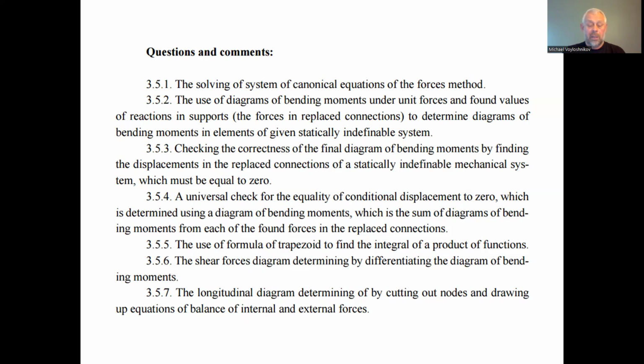3.5.7, the longitudinal force diagram determined by cutting out nodes and drawing up equations of balance of internal and external forces. When we have a diagram of the shearing forces, it's usually not difficult to find the diagram of the longitudinal forces if we do not have a distributed longitudinal force, for example, and we just assume that the diagrams of the longitudinal forces are linear on the segments of the mechanical system.